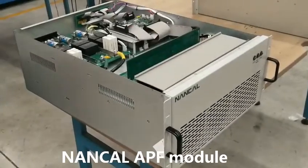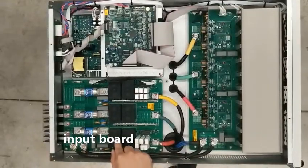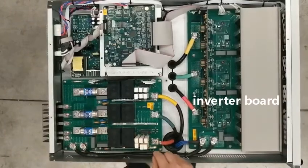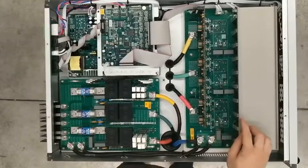This is the internal view of the power module. Three-phase line voltage goes through the fuse and the relay, and then goes to the inverter board. The inverter board includes all the drivers for the IGBT, the IGBT module, and the capacitors.